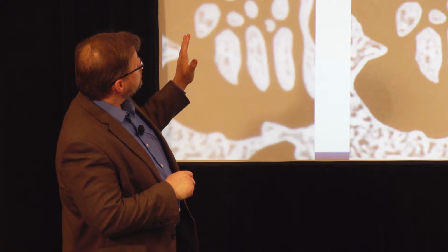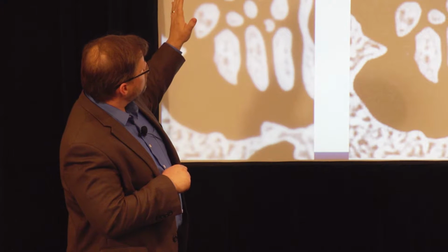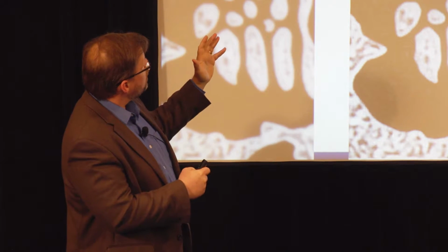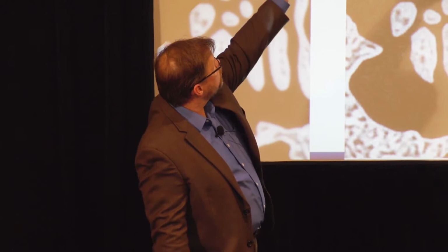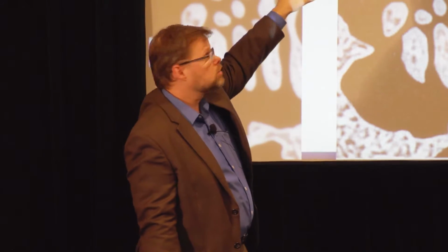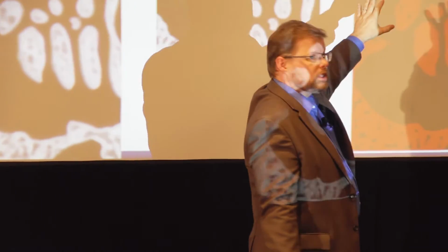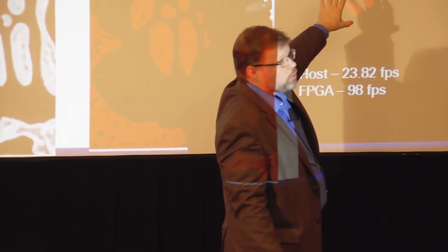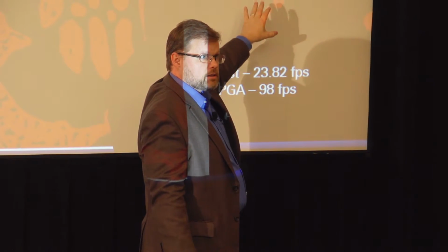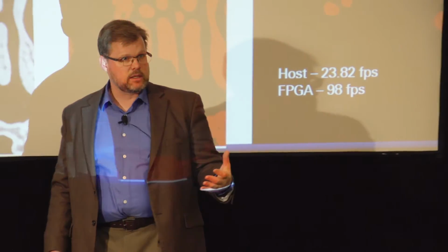It moves from this grayscale domain, the image itself gets crisper through a process called convolution, and then it gets thresholded into a binary image, and then morphology and filtering happen to count the blobs of a particular size. It's a pretty common vision technique. It's been around for 20 years.